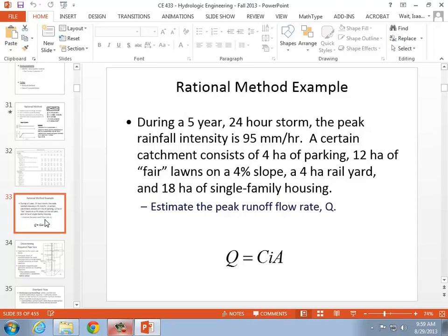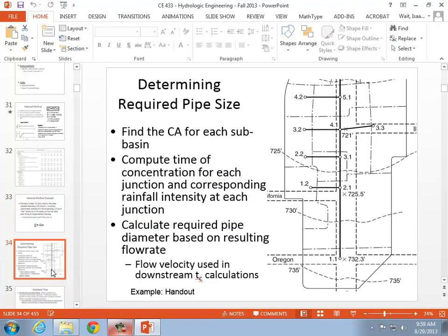What we'll do is we'll look up the rainfall on that day because I've got access to the rainfall records for the Huntington area going way back, and then we'll look at what's called an intensity duration frequency chart that has a graph of how big of a storm qualifies for what return period. So we'll look that up if you'll remind me. That's a good question. Based on the damage that it caused, it sounds like it was probably around a 100-year storm.